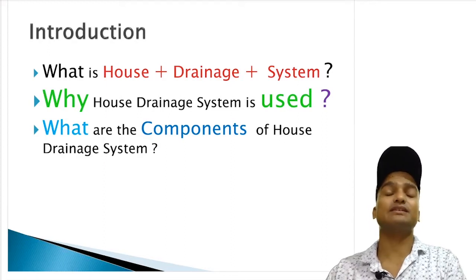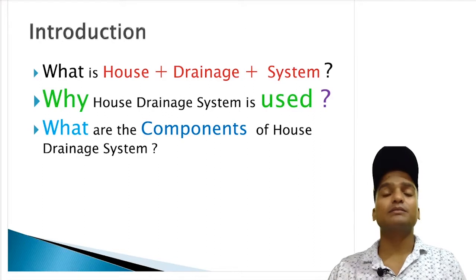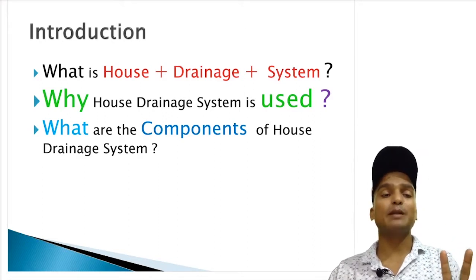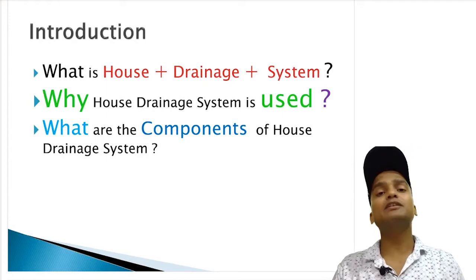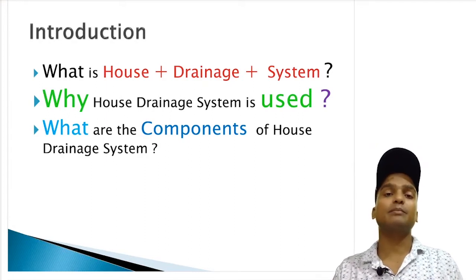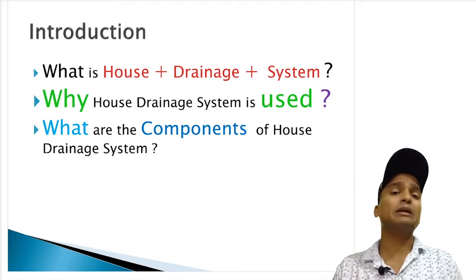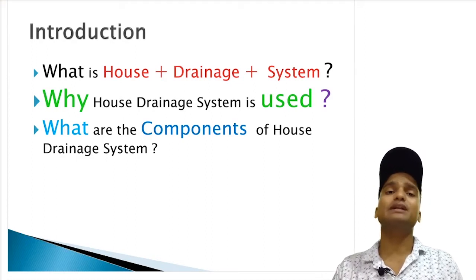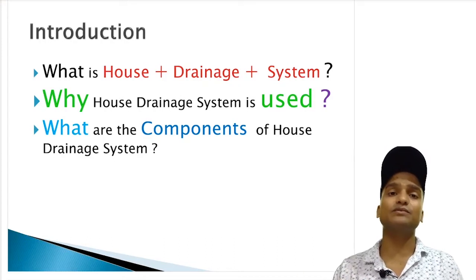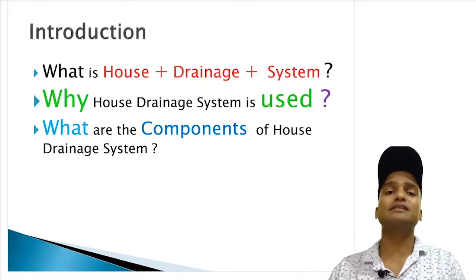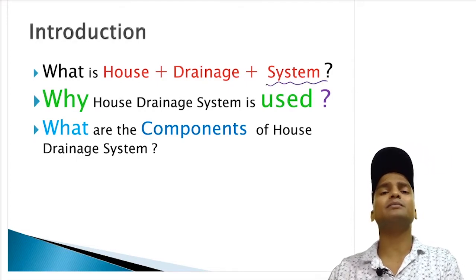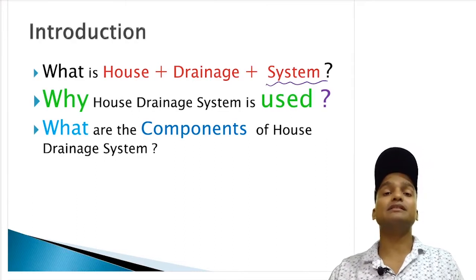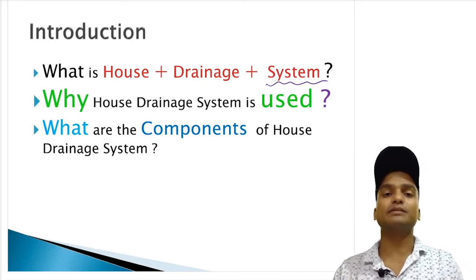And then the drainage. Drainage is important because there are 2 functions in the plumbing. One is the supply and another is the drainage. For supply of water you need pressure. The pipe carries water under pressure, but drainage does not require pressure. It goes simply under gravity flow. Alright, so this is the basic difference, and for this also we have to provide a certain system. Otherwise, if the system is blocked, then the path of inflow is there but the outflow is blocked, and the entire system will be choked.